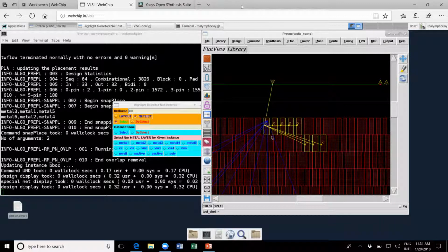We can see that the clock net comes in, gets to the 8 buffers, and then each of these 8 buffers drives another 8 flops, I think, because there are 64 flops in this design. It's a 16-bit multiplier, so 16 inputs, 16 inputs and 32 outputs, so 64 flops in total.